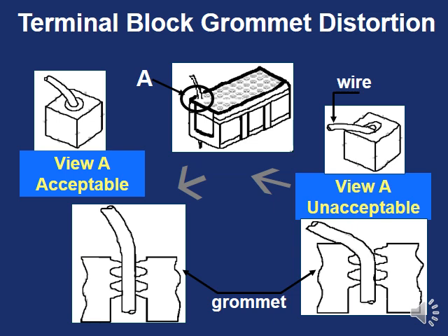Sometimes terminal blocks, when they're installed, the technician might install them with not enough slack. There should not be any tugging of the wire. The wire should be nice and loose outside of the terminal block.